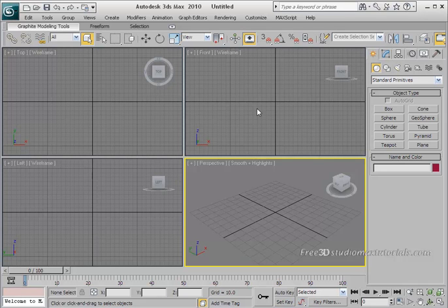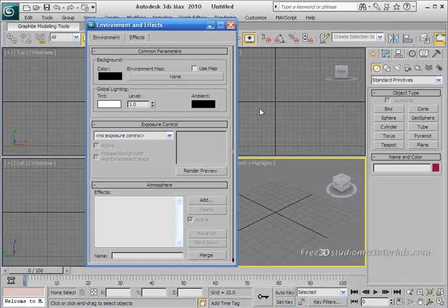So all of us just choose your favorite sky photo for the background. I'm choosing just what I like. So let's add a sky image to the background in 3ds Max. Open your environment settings, hit 8 on your keyboard, and the Environment and Effects dialog box will appear.